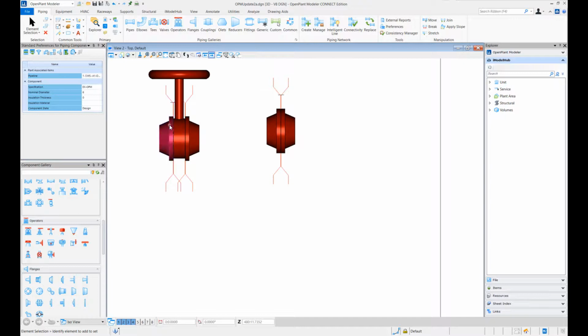So I can continue to connect multiple wafer-ended components together, and each will have a gasket inserted. But once we close the connection by joining a mating flange, only then a through set of bolts will be inserted. Besides this, we have what we call lug joints.